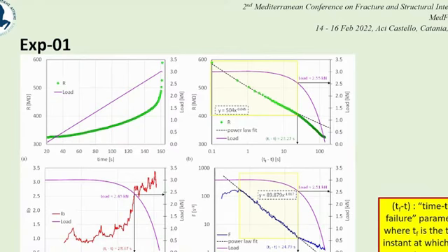The time to failure parameter provides better clarity on what happens during the last seconds before the occurrence of the catastrophic fracture. Notice here that a power law emerges from the 23rd second before the fracture. You can see it here with the yellow box.